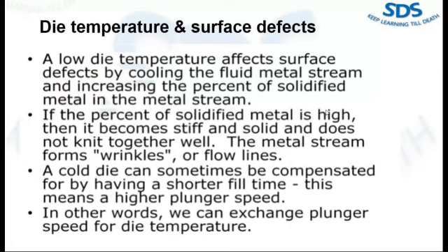Okay, so many times the effect of a cold die can be minimized by filling the die faster, by using a high plunger speed. So are there some negative consequences when the fill time is reduced? Yes, but it can often reduce surface defects when the die is cold.